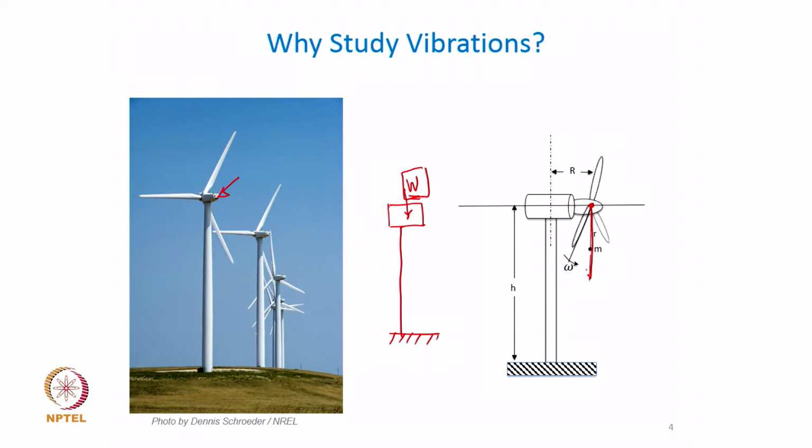A force which will act on this bladed plane is going to be a centrifugal force based on the net unbalance in the rotor, and will be dependent on the square of the rotational speed. Now, this force is going to be varying with time. So, it is a harmonic force acting at this particular location in the rotating shaft, and so we can expect it to be a harmonically varying dynamic force, and that dynamic force is going to create interesting forcing on this